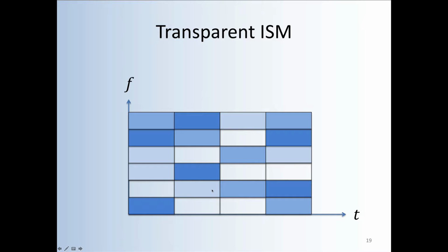Now this type of signal that I've shown here is actually what we do on Earth in today's modern wireless communication systems, such as the mobile cellular system and the Wi-Fi system that you use to connect your computer to the network. Both of these, and in fact I can safely say that any wireless radio system that's designed today would utilize a signal with a structure with a lot more complexity and bells and whistles added to it, but with this basic structure for exactly the same reason that we're using it here. And this comes under the name of orthogonal frequency division multiplexing, or OFDM. So it wasn't always the case, but today there's a consensus that this is the best structure to use for a signal for earthbound wireless communication systems. And so that gives additional validation for the merits of this approach.